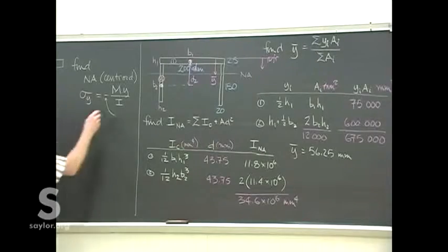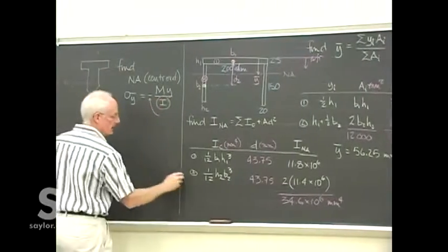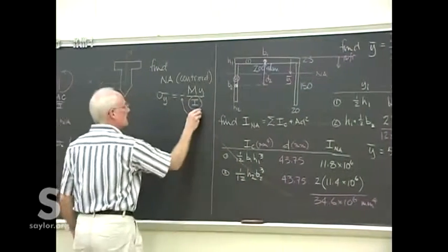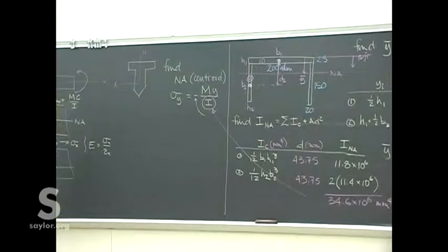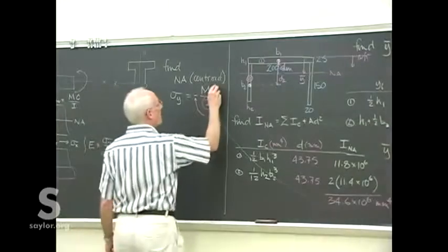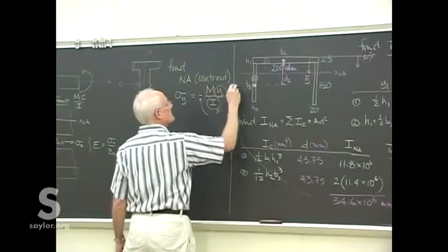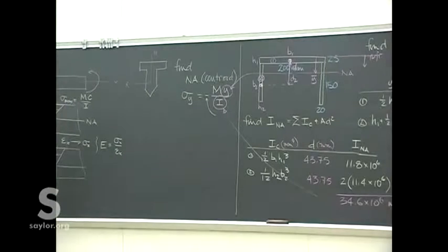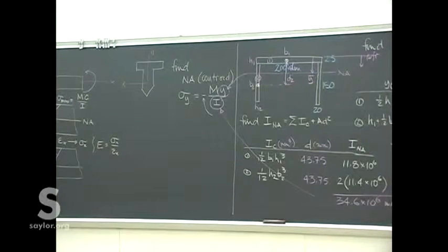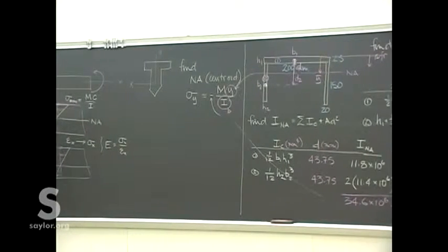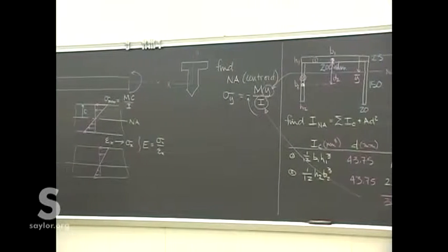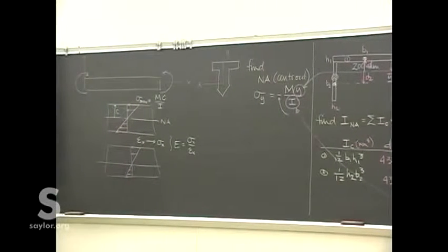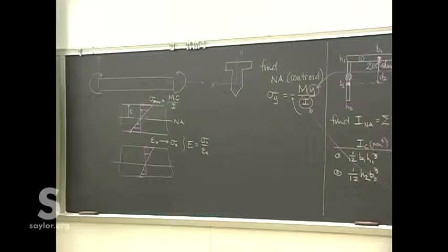And now that gives us the I that goes into there. The Y is measured from the neutral axis. And if we had some given load, then we could figure out the stress at any point across the solid. Does that look a little familiar now that we kind of flew through that in sort of a skeletal way?